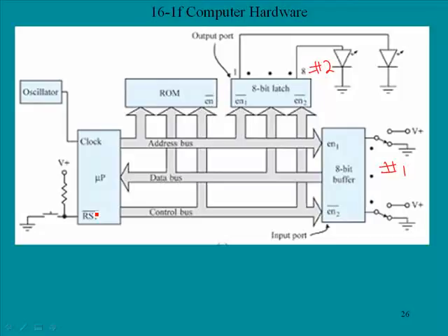Instruction execution in this case is a matter of transferring the last 2 bytes received and held in temporary storage into the program counter. Remember, the program counter always points to the address of the next instruction. Since we are now forcing it to 0000, that hex value will be the address of our next instruction, which happens to be where we began.